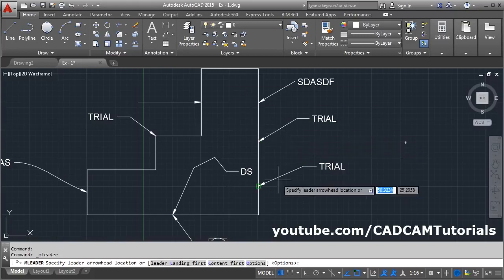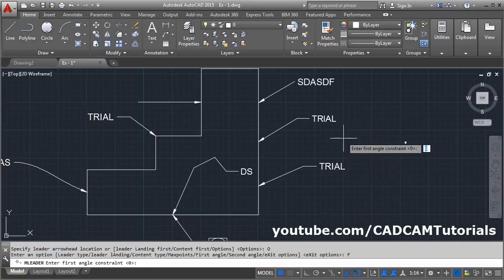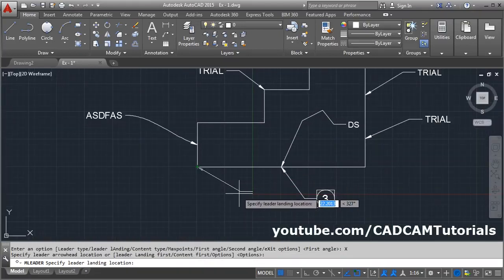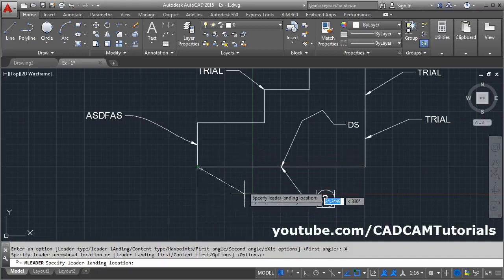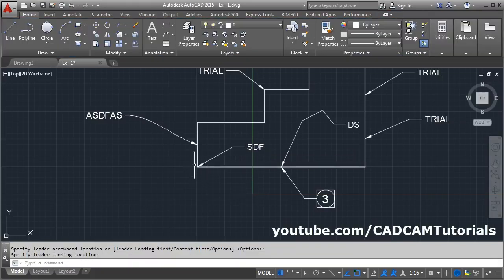Again leader, options, then you can define the angle, first angle. Click on this first angle, then give the angle. I want it in the increment of 30°, enter, click on exit option, then give the first point and take your cursor. As we take cursor above, it will switch directly by 30°. That means it will be incremented by 30° each and every time we move the arrow. Click once the desired position is achieved, give the text. This arrow is created at the angle of 30°.